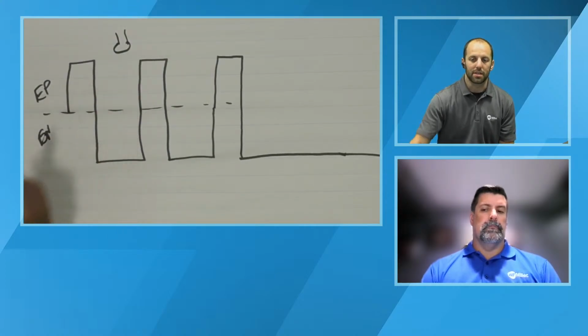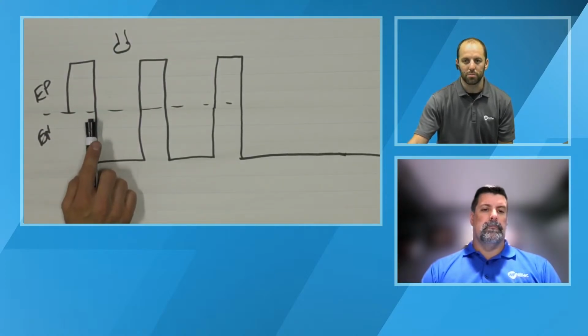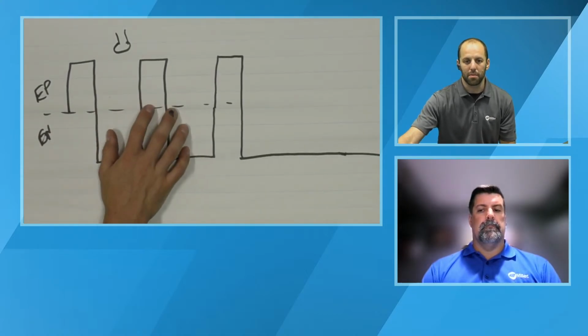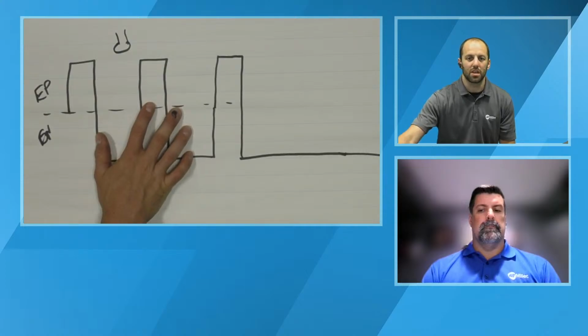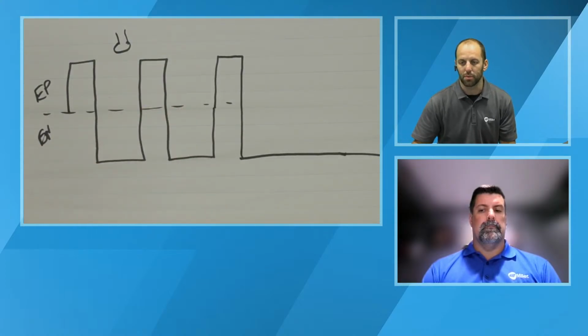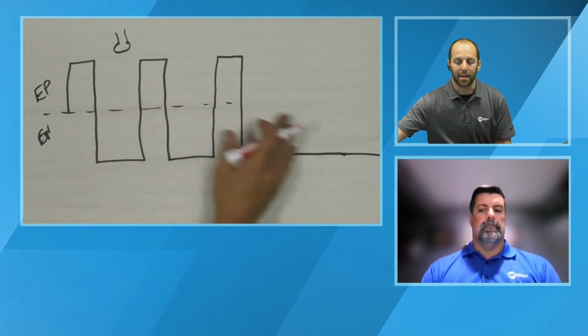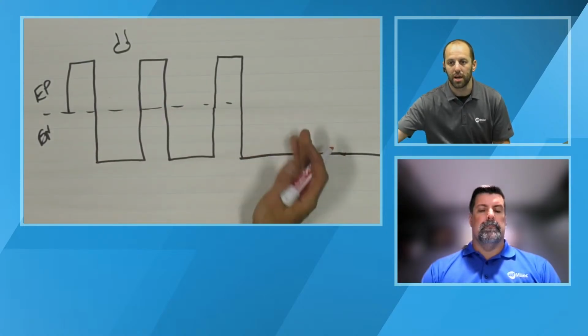What I would like to say about this is what we found through some internal testing is that we can largely accomplish the same effects of this utilizing our independent amperage that we talked about just 5-10 minutes ago, ultimately skewing and adding additional heat on the electrode negative side, rather than adding an additional variable to our welding process.